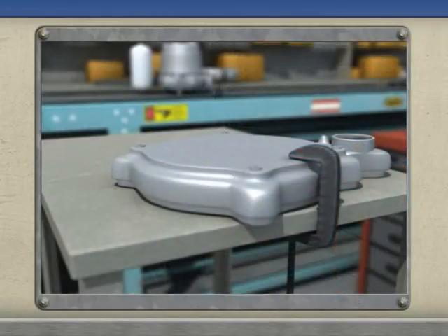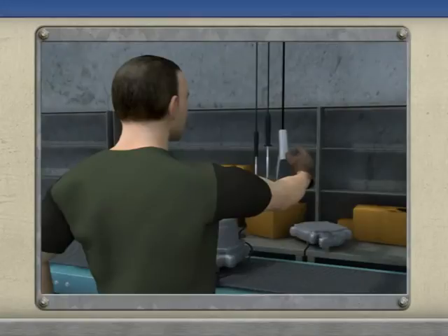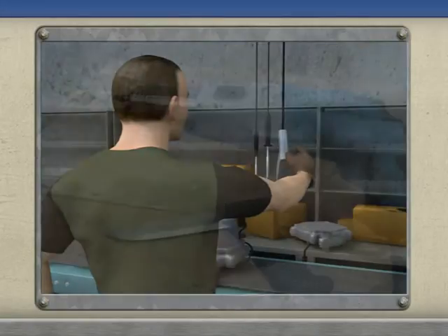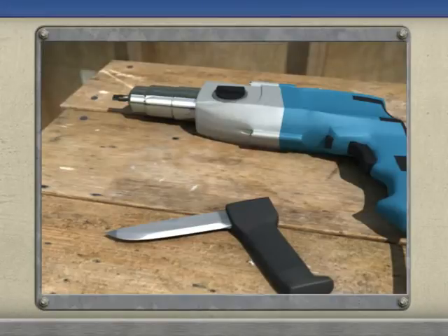Changing the way parts, tools, and materials are to be manipulated. Examples include using fixtures such as a vise or clamp to hold a workpiece, which relieves the need for awkward hand and arm positions, and suspending tools to reduce their effective weight while allowing the worker easier access to them. Changing tool designs. For example, pistol handle grips for knives to reduce wrist bending postures required by straight-handled knives, or squeeze grip actuated power screwdrivers to replace finger trigger actuated screwdrivers.